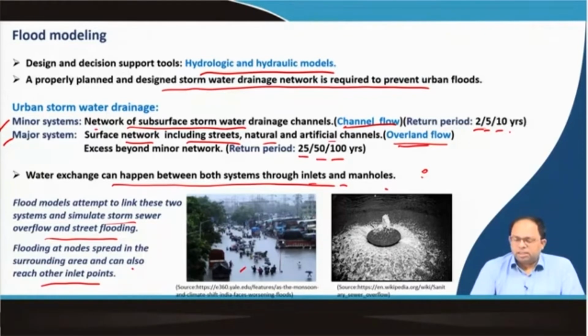You can see this manhole is raised up and water is coming out of the manhole. So, that means even though there may be no rainfall in this area, maybe rainfall is happening in some other area. So, the water is traveling along to this manhole, right, and the water that is reaching that manhole, or estimated to reach this manhole based on the time of concentration and the catchment area, probably exceeds the diameter of the manhole, and that means this profile or section of the manhole is not able to take care of that, and water starts coming out of this manhole.